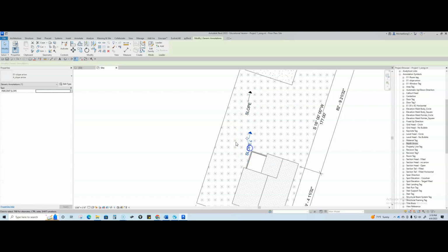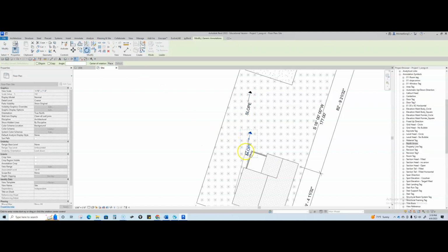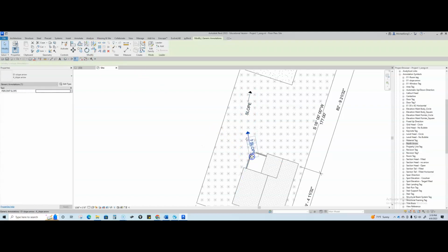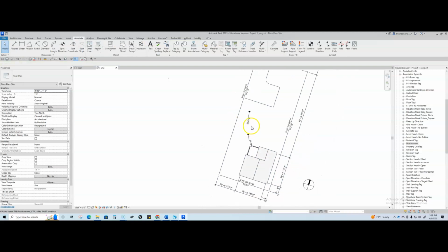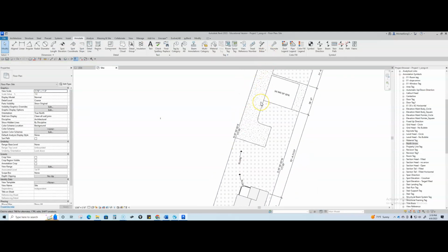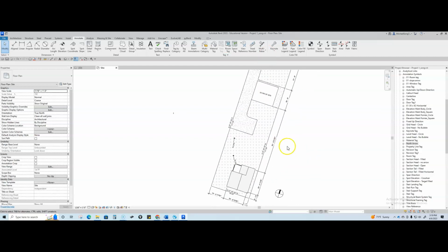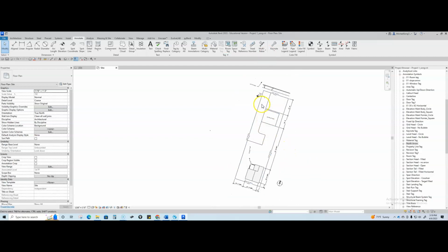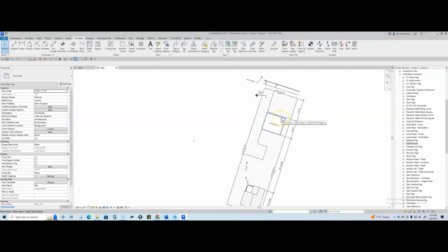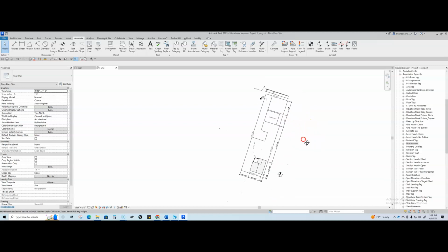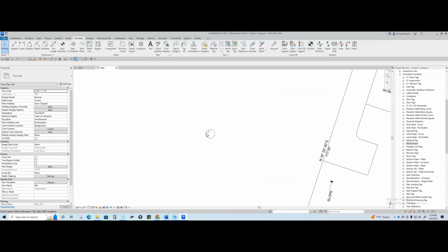Generally speaking, most plan checkers like to show the slope pushing away from the property, and then a certain flow line, basically. So go ahead and add all the slope. You have the north arrow, the spot elevations. Try to make it as close to the PDF diagram that you see. But let me see, what is this?